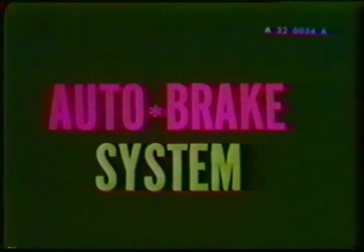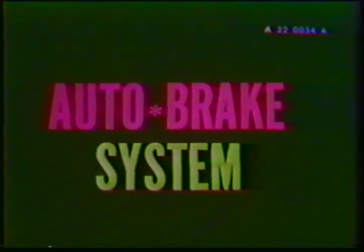Now, let's cover the A300 auto braking system. It is a system that permits auto brake application without brake pedal deflection. The advantages gained by using this system are: it relieves the pilot of the braking task to get optimum deceleration according to aircraft weight and runway length, and improves tire and brake wear. It also reduces the stopping distance in the event of an aborted takeoff and improves passenger comfort due to a consistent deceleration rate.